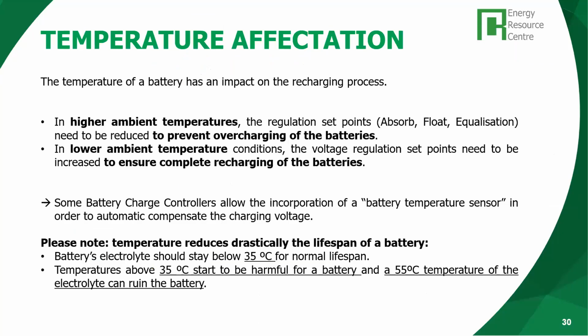The temperature is very important. It affects the performance of a lead-acid battery. When the temperature is very high, above 35 degrees Celsius, it can start to be harmful for the battery. And even higher, 55 degrees, the electrolyte can get very warm, not quite boiling, and then it can also destroy the battery, even the separator of the cells.